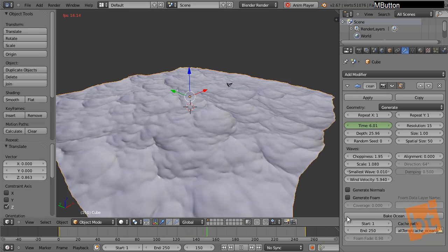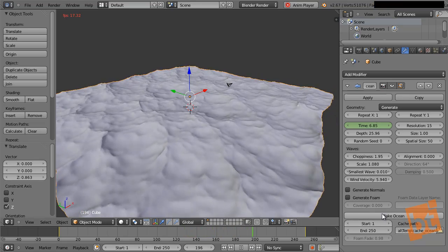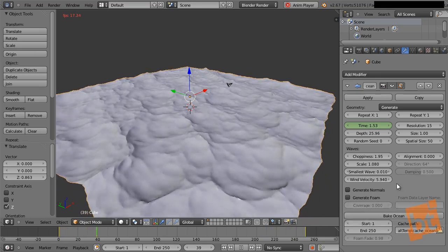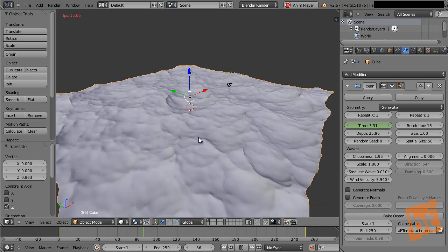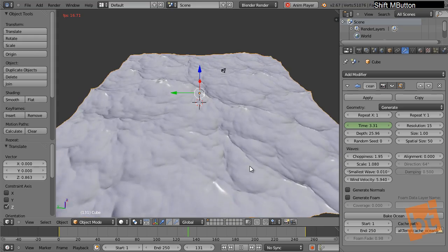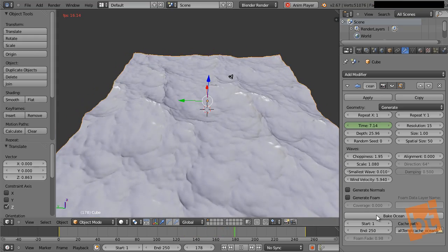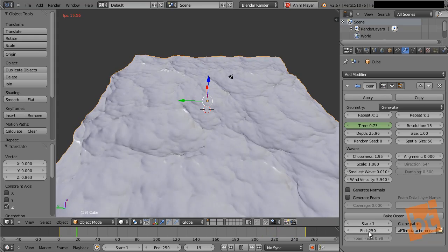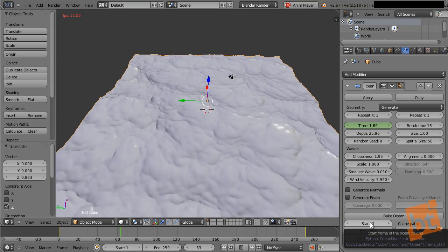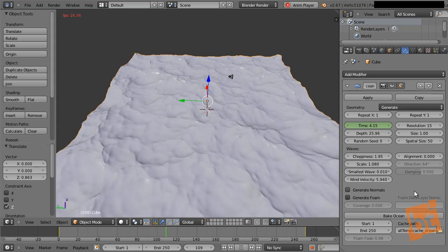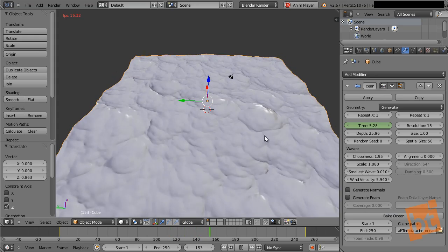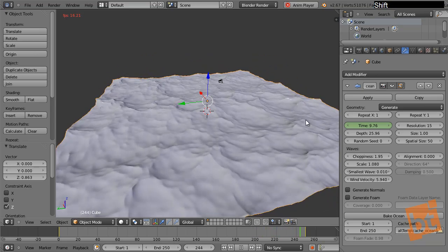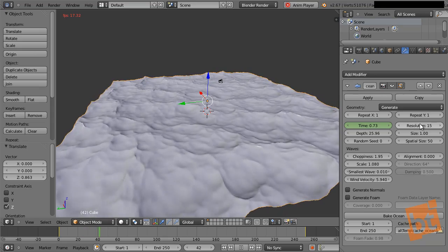We have these other values here, and you may be wondering what the bake ocean option does. And well, this is kind of simple. We can generate normals and generate foam from this ocean. And I'm going to explain to you now what this means. When we bake the ocean, in this folder, we generate an image sequence that covers this range of the animation, and it will generate EXR files with displacement, right? Which is basically what the ocean modifier does, the displacement of this mesh. And the size of the image will depend on the resolution here, right?